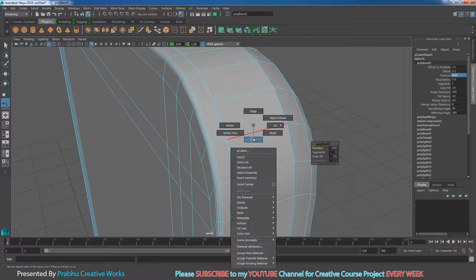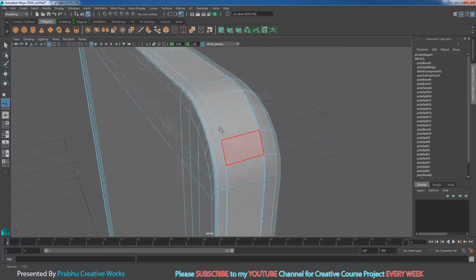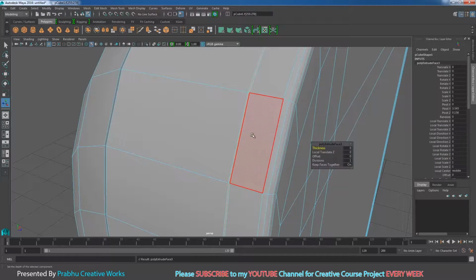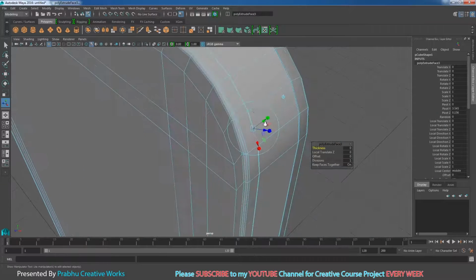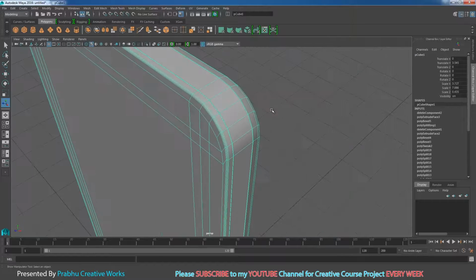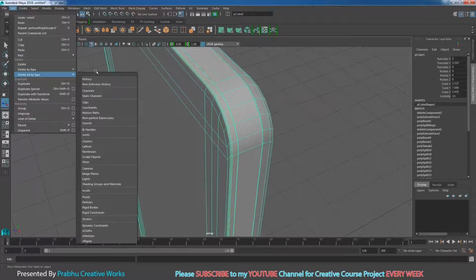So shift right click and choose face. I will select the single face, shift double click on this face. That means the whole loop will be selected. See here. Shift right click and choose extrude face. So you want to extrude in Z and press delete on the keyboard. Right click and choose object mode. Now go to edit, delete by type and choose history.